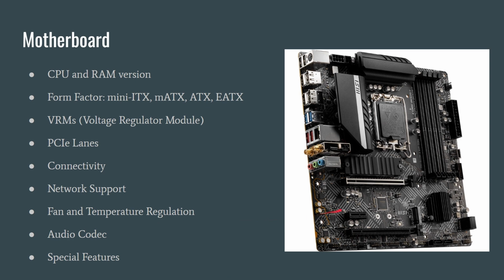But then also importantly, your motherboard will note that it has a specific amount of temperature sensors all around it. And these temperature sensors are placed to monitor the heat in the computer. So the more of these you have and the higher quality they are, this will mean that your computer will get a more accurate reading of what the temperature is like inside, and that'll allow it to more accurately tell the fans what speed to run at. So those are just some important things to consider. Usually there's no one motherboard that's really bad or really good at this. They're all pretty much similar. But it is just something to consider. Like, don't buy a case that comes with 6 fans if your motherboard only has 4 fan headers, right?